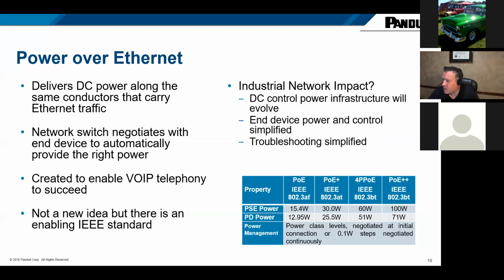Then Cisco actually pioneered a 60 watt. They called it UPoE for a while, and that was really the first entrance into Power over Ethernet lighting. That eventually migrated into the standards bodies and became the 4PPoE standard at 60 watt, 51 delivered. But in 2018, PoE++, which is 100 watt technology, 71 at the end device,